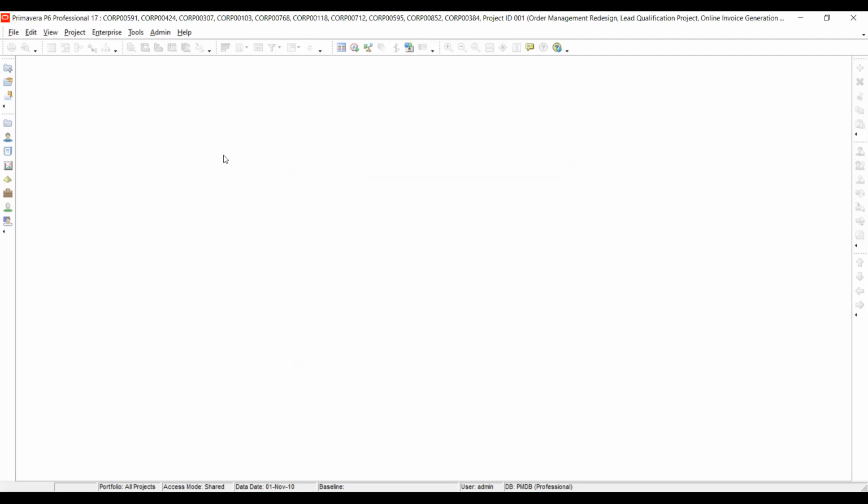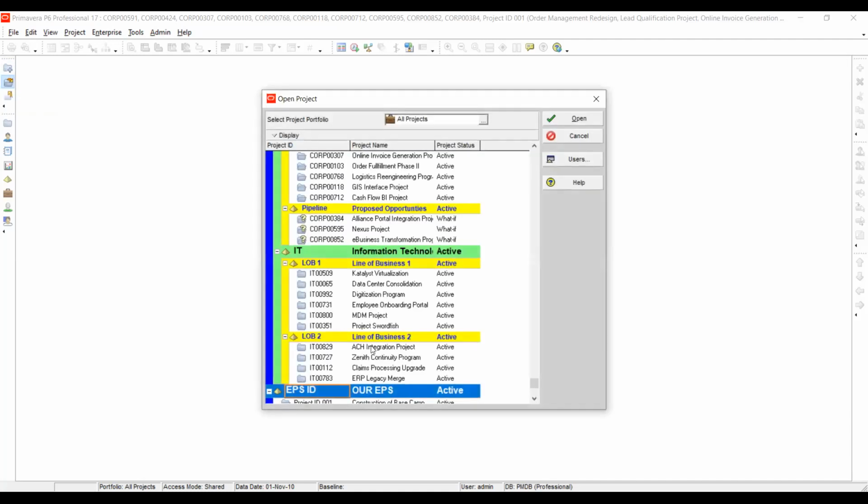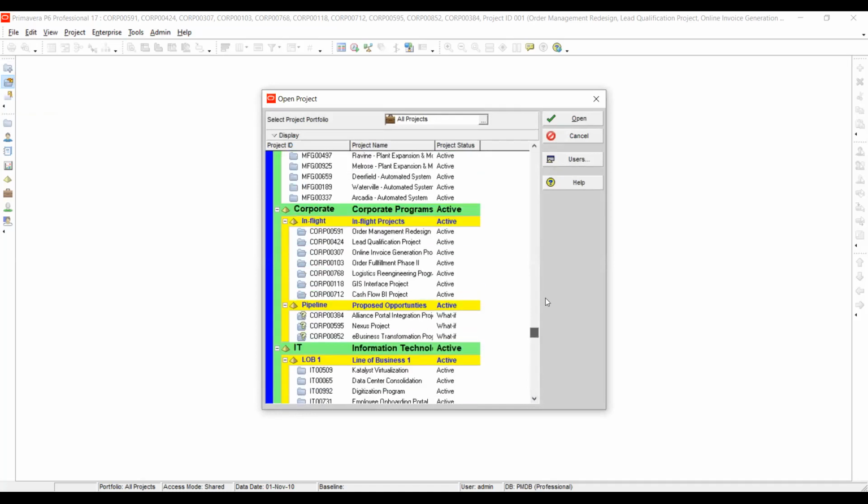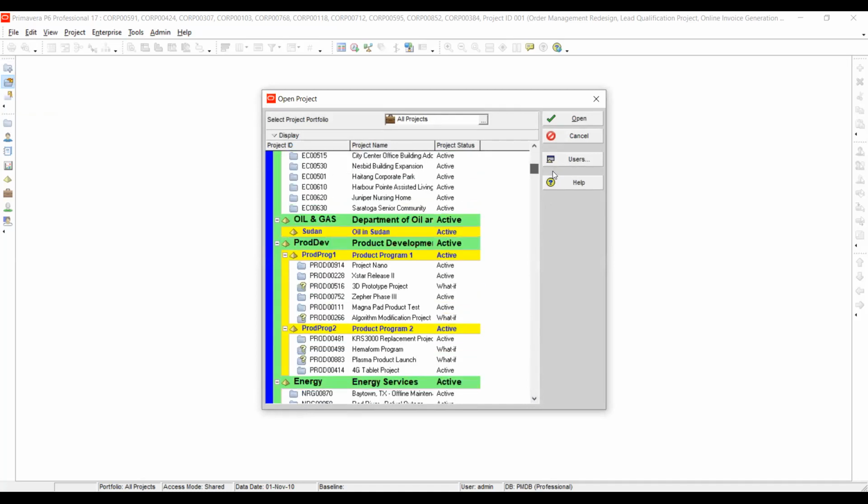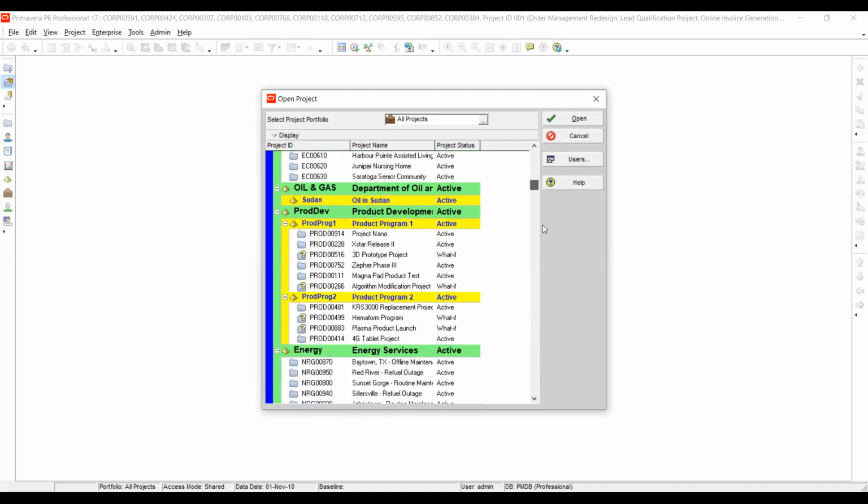So where do we find our projects? Because we need to see the project we've created. You come here, this was to create a new project, but this is for opening a project. So when you click on open, it's going to show you the whole EPS, all the projects that are there.